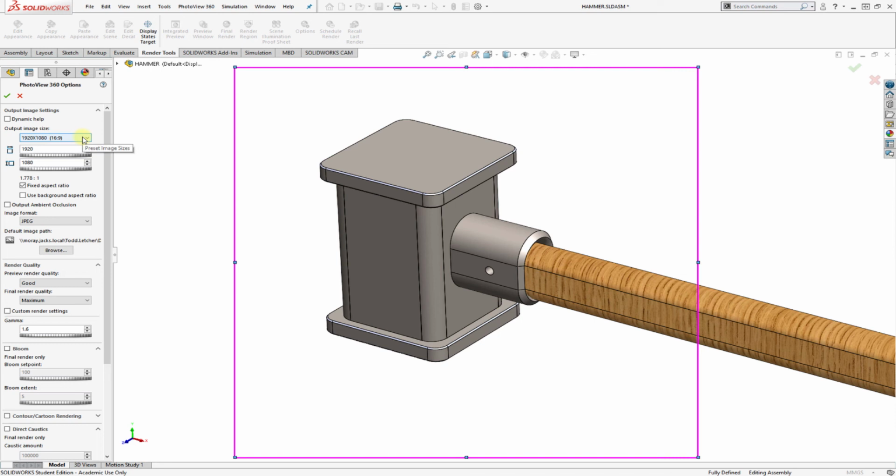So one thing, when we zoomed into that picture, it got a little bit blurry. We're not going to do this right now because it takes a long time, but the way that you could make that better is you could increase your resolution. So if you doubled both of these numbers, I don't know what those are, but if you doubled those, it would certainly get better. If you tripled it, quadrupled it, it would get better. So the bigger these numbers get, the more pixels your image has, the longer it's going to take to render, but the better it will look as you zoom in. So I don't know if that's important for your application or not. You'll have to figure that out as you go.